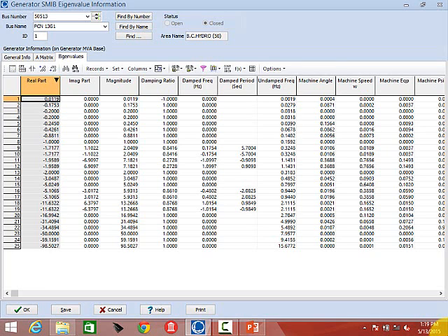Okay, but in answer to why would you care if you're not even sure, I've got a generator that's causing trouble or looking weird. Why is that? I'm not looking for trouble. I'm not calculating all these values, but I've seen one. Maybe I'm doing a large system run like Gordon's doing, and I see something oscillating around. Is that numerical instability? Is that real instability? How do I know? So I go in here and I look and I see, is there a positive eigenvalue? If there is, I might want to investigate what's causing that.